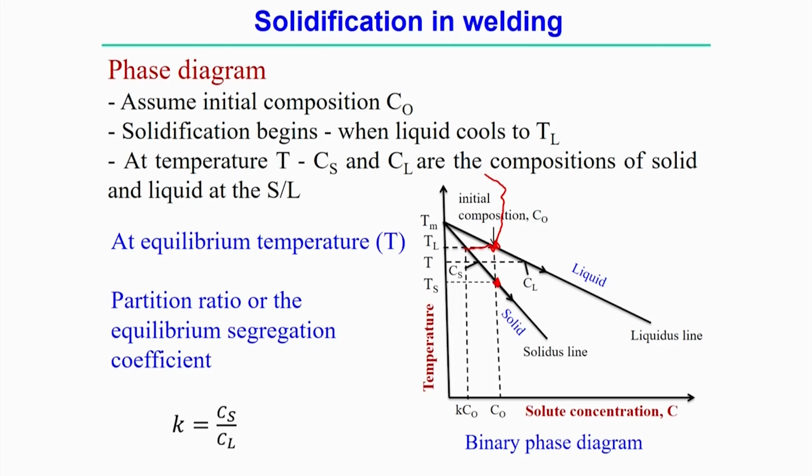At the solidus line the phase is completely solid, but the concentration is exactly the same amount, C0. It simply follows this vertical line, starting at this point and gradually reaching this point, which completes the solidification. We can analyze using the lever rule between the solidus and liquidus temperatures to find the liquid content and the solid content from this binary phase diagram.